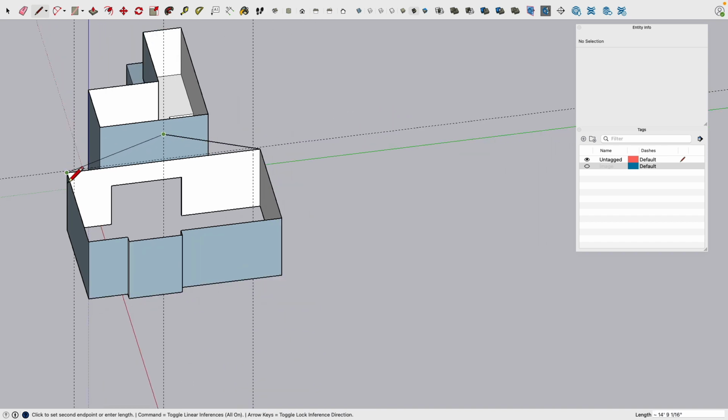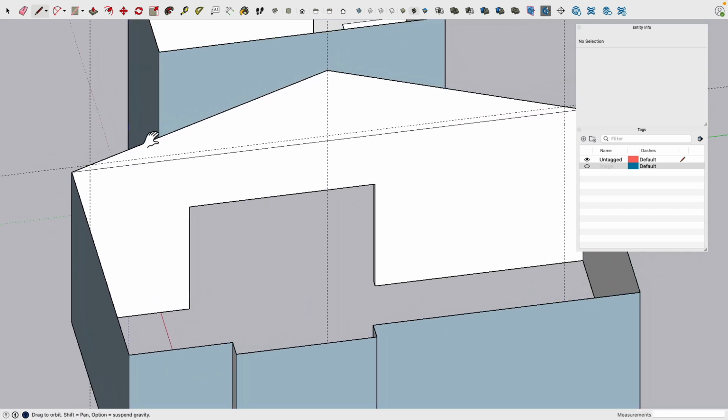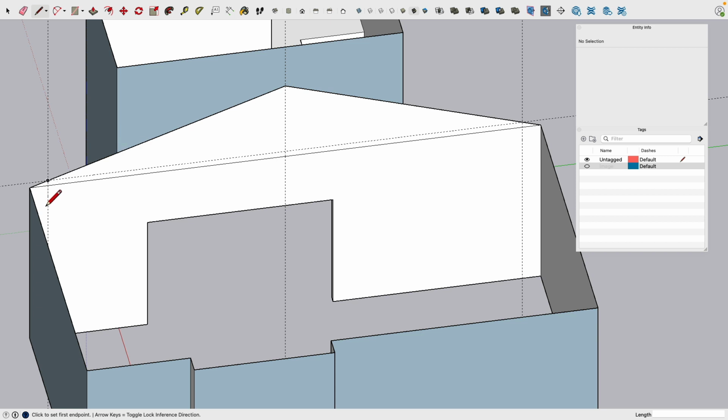Now from there, going to there, yeah, there you see it's all correct now. Maybe when I typed in the numbers, as it happens a few times, SketchUp messes up the entry, and then it uses more what I moved with the mouse than what I typed in. But basically, I have my height point.